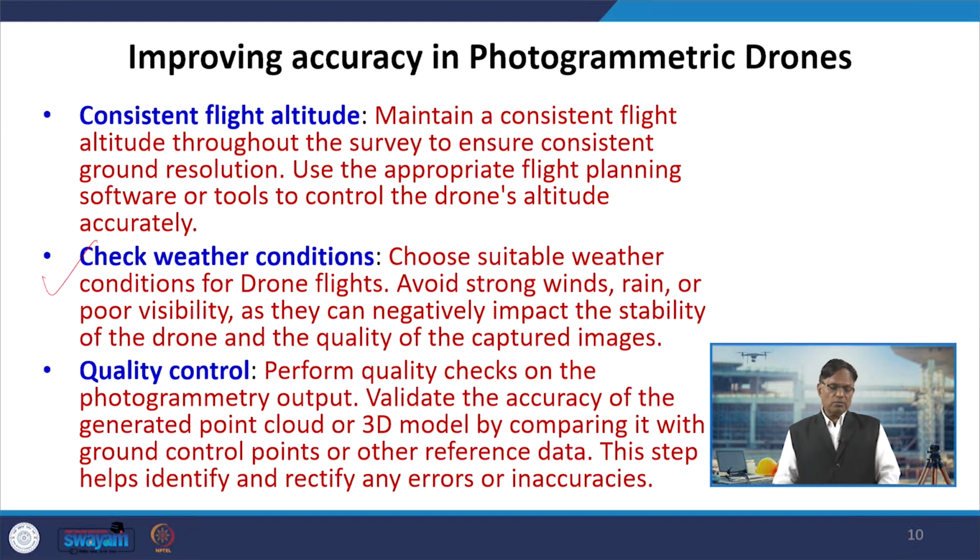Check weather condition. Choose suitable weather conditions for the drone flights. When you are flying over the area, you have to avoid strong winds, heavy rains or poor visibility conditions, as they can impact the stability of the drone as well as the images captured from the photogrammetric drone. So, good weather condition is essential.